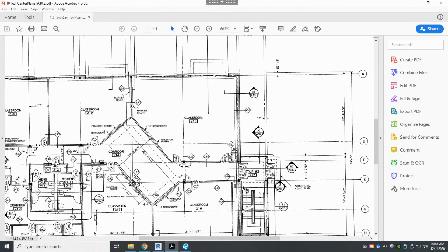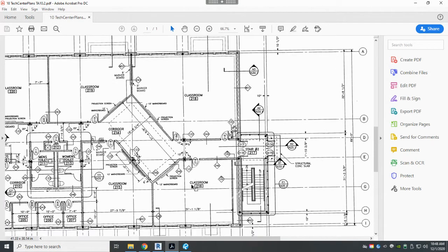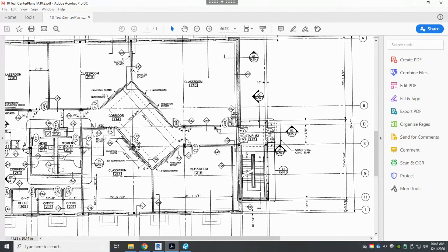So that's how to read those plans and see what could be affected by a diagonal bracing. If I have diagonal bracing in the wall, it's going to start really low on one end of the wall and go up higher on the other. So it's going to restrict my movement of placing openings and doors and things like that on that bracing wall. I also can't just assume that I can run any kind of piping inside that wall too. So that's important to note where those locations are.